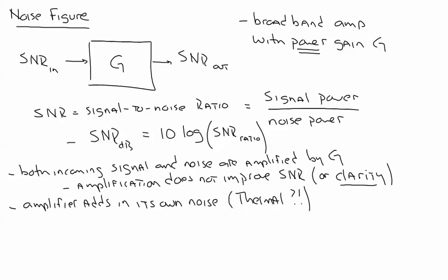So here's an experiment you can do. Go home, if you have a home stereo. Turn all of the input sources off. Turn off your CD players, your MP3 players, whatever drives your power amplifier. Turn the volume control on your power amplifier to 0. Turn your amplifier on, make sure it's connected to your speakers, and start turning the volume up. What you're going to hear, even in the absence of any signal driving your power amplifier, is hiss coming out of those speakers. That's noise. It's probably mostly thermal noise because your amplifier is not sitting at absolute 0. Okay.